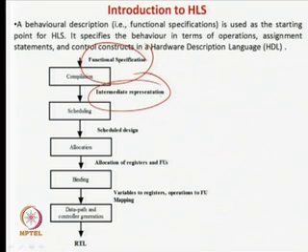Then here also sometimes we do a lot of pre-processing, as we have already seen, to get an optimized design, because the functional specifications we are writing are basically manually driven procedures. So, they are done manually, and sometimes we require optimization. Then the first stage is that we go for scheduling. We will see in detail what scheduling means. Scheduling means that for each of the operations we give a time step, that this operation will be done in this time step and so forth.